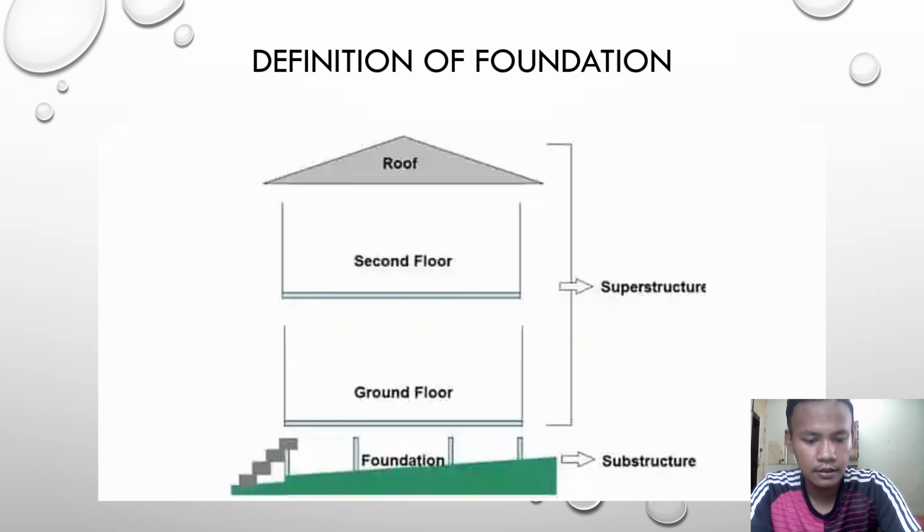It's utilized to support light structural loads on soils with suitable bearing capacity. The width of the wall determines the size and location of the strip foundation. Besides, mat foundation is another name for raft foundation. It extends across the entire structure, providing massive support for enormous structural loads.